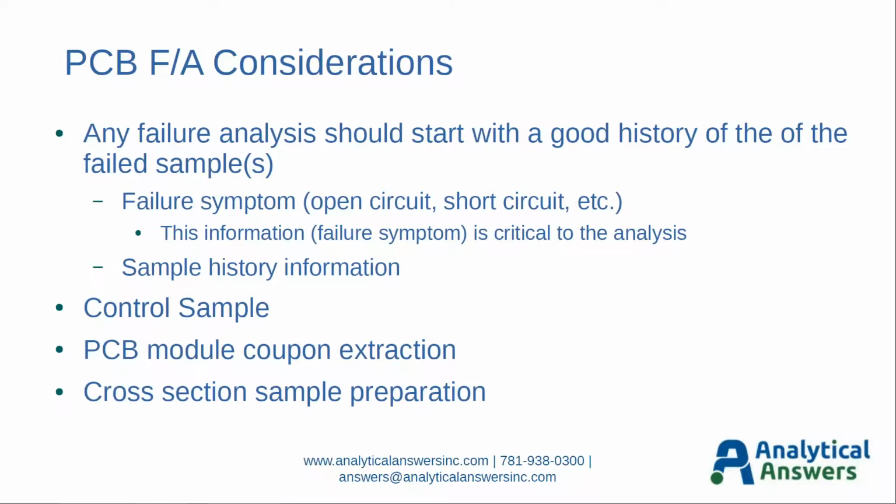The next thing is we want to understand the sample history. Was this infant mortality? Was it a burn-in failure? Has it been in the field? How long has it been in the field? Was it one particular geographical location in the world that we're seeing this failure, etc.? What is the approximate failure rate? All these things are important to know before starting any failure analysis.